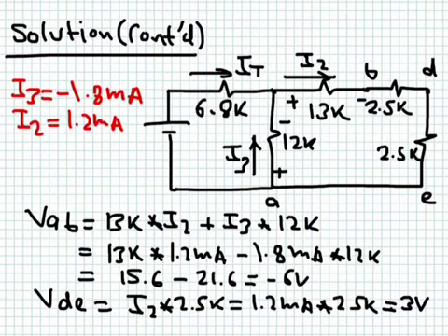Now, I mentioned to you in class, in order to calculate VAB, the voltage difference between A and B, you have to find a path along the circuit. Take any path that you like that connects point B to point A. So I have to go from here to here. I will take this path here, okay? Of course, you are most welcome to go around. Maybe you can take this one to verify the answer. Or you can go this way. Okay, all of them should give you the same answer. Okay, I took the shortest one.